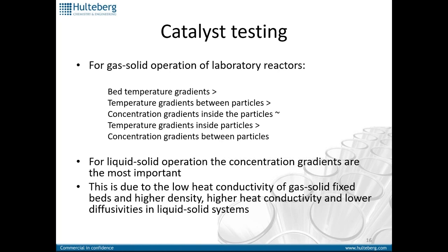In liquid operations, so if you have a liquid reactant and product and a solid catalyst, the concentration gradients are the most important. In liquids, you have much higher heat conductivity. You also have much lower diffusivity, so you have much lower movement of the molecules, compared to the gas phase system. So yeah, that influences that.